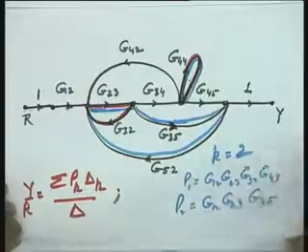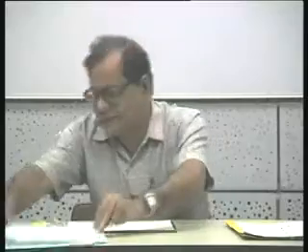Yes please. So what's the G44 doing in the actual loop diagram or in the actual situation? Yes, a physical situation. I will like to give the equivalent block diagram because in block diagram this loop will become very clear. But remember, I told you that this is a created situation so that the signal flow graph formula becomes more clear. That is why its corresponding physical control system was not given. But yes, visualization will become more convenient if I look at this particular loop in terms of its block diagram.